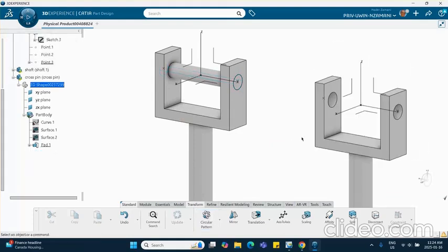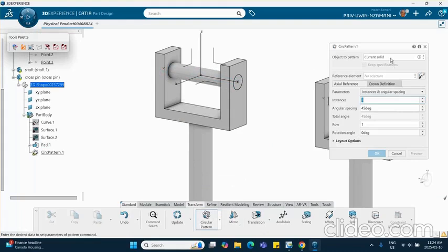Cancel that. All right. So what I want to do is to create a circular pattern here. So I found a circular pattern, not the whole solid. I just want this pad. Okay. And the reference is going to be this vertical axis. Complete crown. Let's see if this thing works. Okay, so I don't want, I just want two, maybe one.